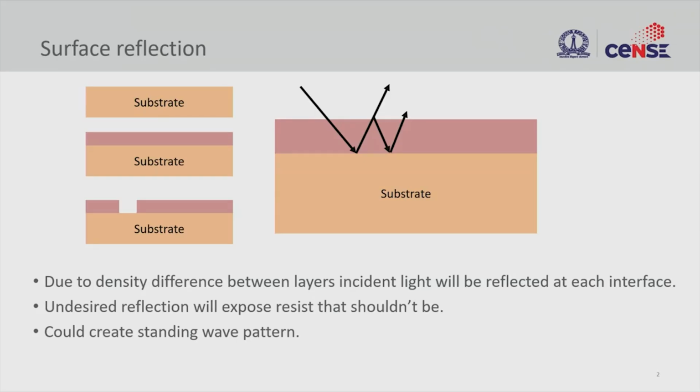So when you take a substrate and coat it with photoresist here, and then you illuminate, and then we create a trench. This is a very simple process, and this is achieved by illuminating it, let's say through a mask. It could be contact mask, or proximity, or this could be projection.